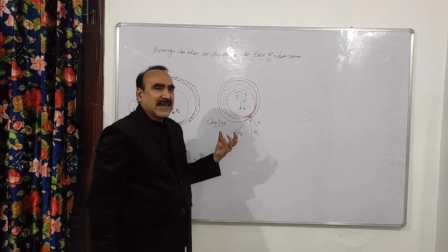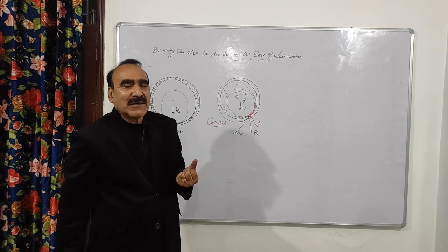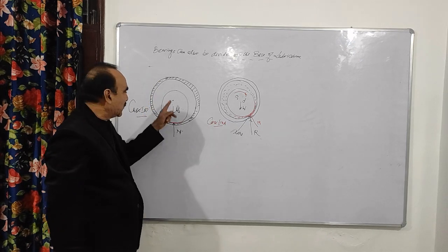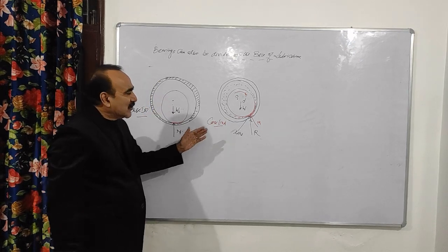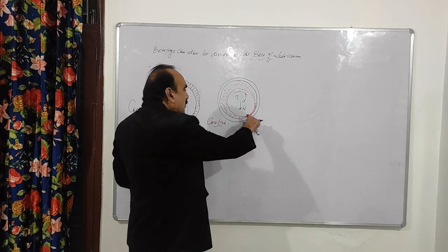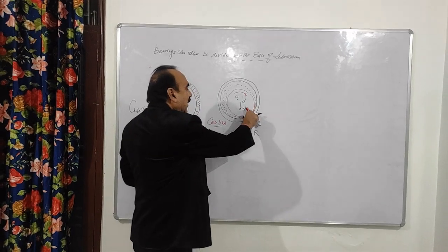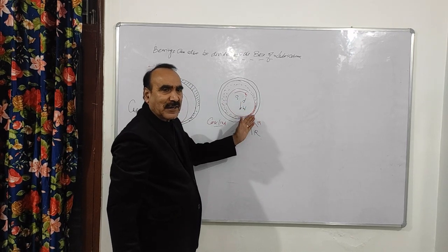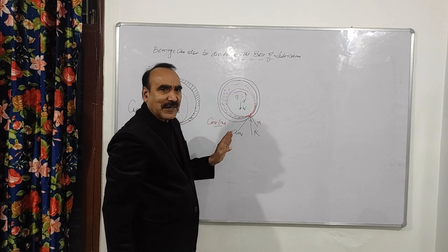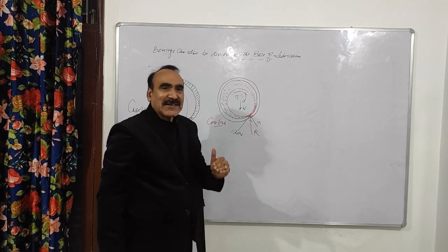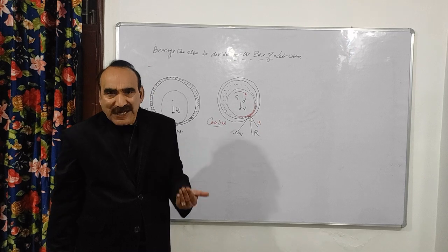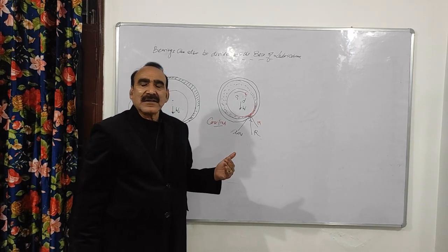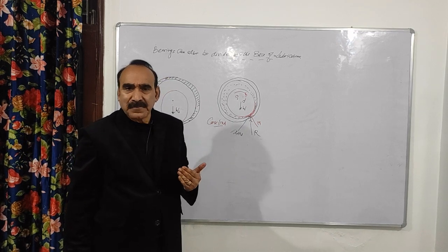Now in this case, how is the load of the shaft supported? In the earlier case, the load was supported by the normal force. In this case, look, the normal force is acting in the upward direction because the load is acting in the downward direction, so the normal force is acting upward. Now because it has just started rotating, and there is metal to metal contact there, it means a frictional force will develop, right?